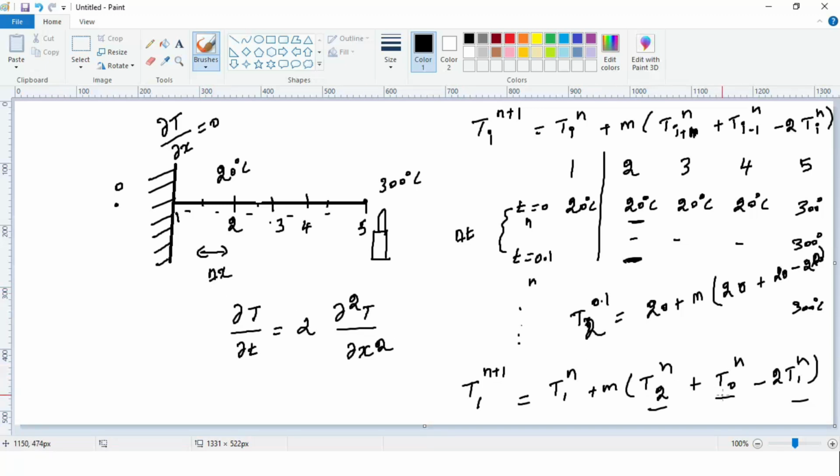For that, I'm going to use another boundary condition. It is called a Neumann boundary condition. There is no heat flux beyond this point. For that, I'm going to apply this governing equation at the zeroth node. Here I'm going to apply a simple central difference: T_i plus 1 minus T_i minus 1, sorry, it is not n plus 1 since I'm focusing on the space domain.